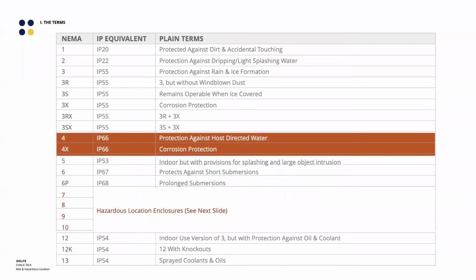And if you look at our spec sheets for products that have wet location ratings, we'll actually list both IP and NEMA. And because of that strangeness, that higher NEMA numbers don't necessarily mean more protected, if it has a NEMA 4 or a 4X rating, it's also going to have a NEMA 12 and 13 rating as well. And you'll see that represented in the spec sheets. And we can do that because of the fact that the NEMA ratings are a little bit goofy. But you can actually see here that, for example, NEMA 5, it's a bigger number than 4. That might infer more protection, but it actually doesn't.